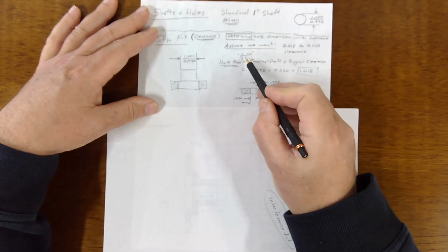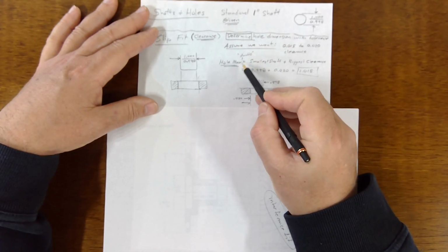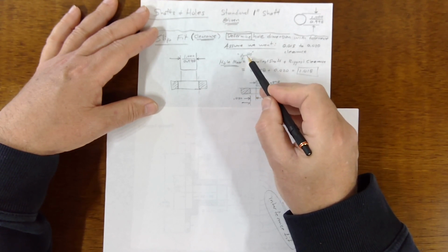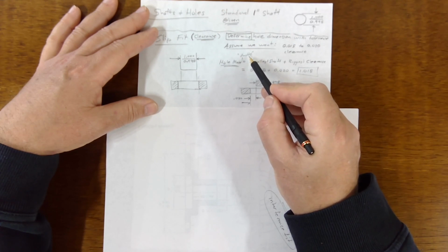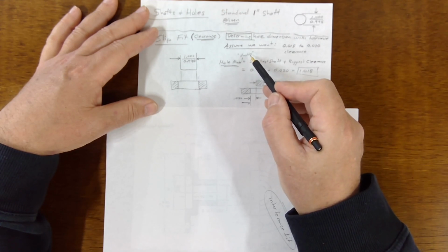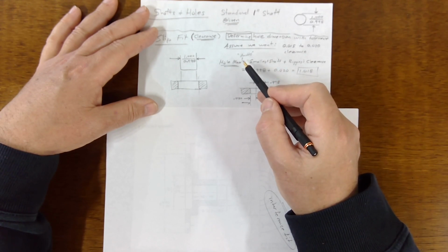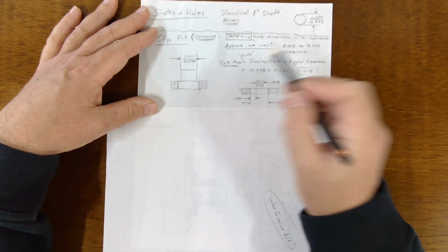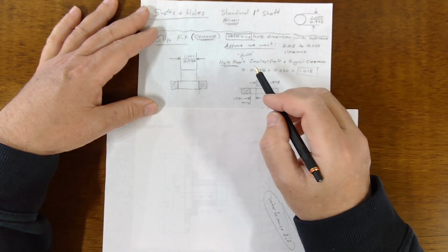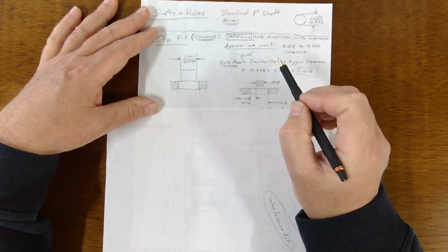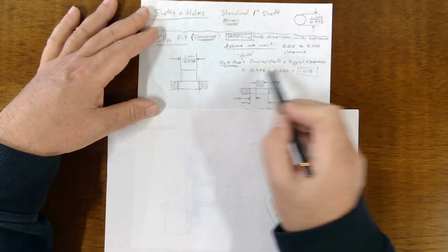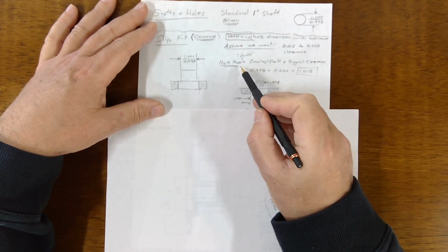So keep in mind, this is the maximum allowable hole. It's not the maximum possible hole, but what we want is the maximum allowable hole. That is, how big can we make the hole such that when we put in a part of a different size, the clearance is still acceptable. It's a little bit confusing, and it's actually possible for me to talk about this too much. So just follow these examples.